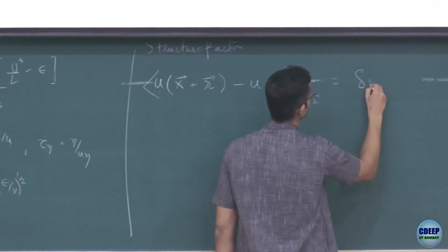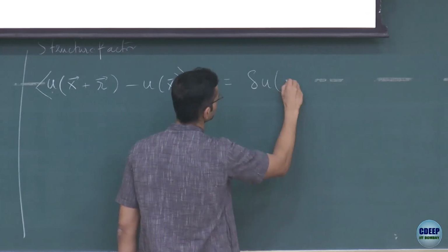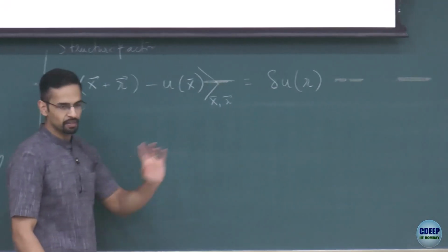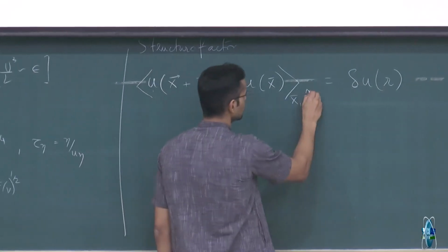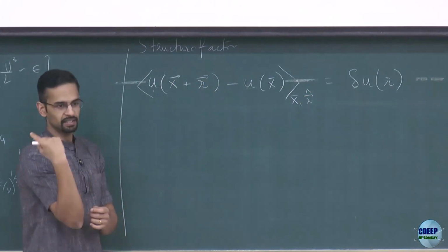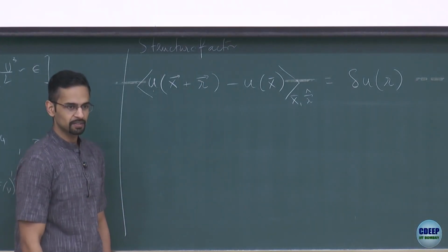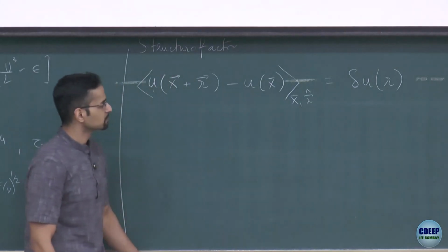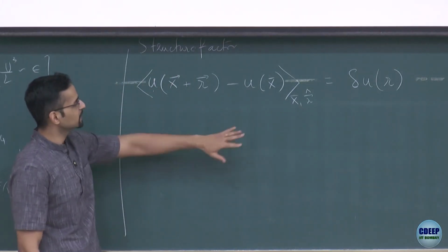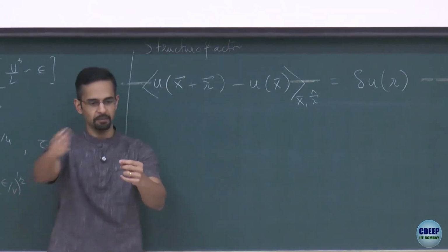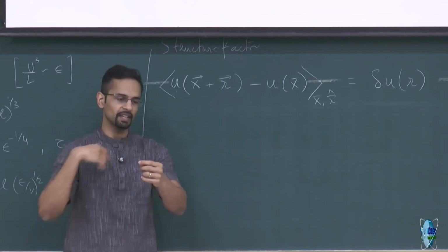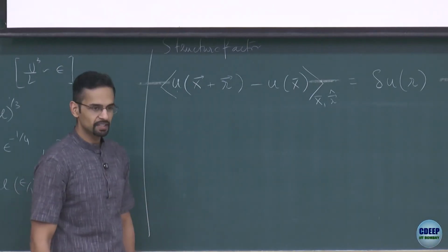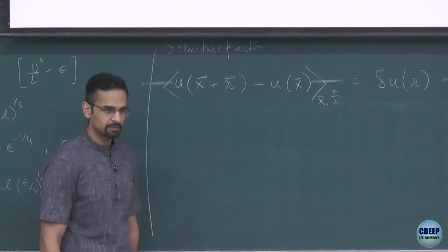So then I will get a structure factor, or a velocity difference, that depends only on the magnitude of r. When I vary r, I'm really varying only the orientation, so I should say varying the directionality of r, not the magnitude. I'm keeping it at different magnitudes, but then I'm averaging it over space. At any point in space, I can make a ball of size r and take the difference of velocities. I can do this all over space, so this will give me the equivalent of an ensemble average.